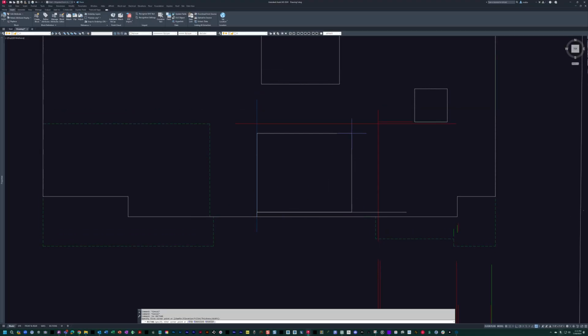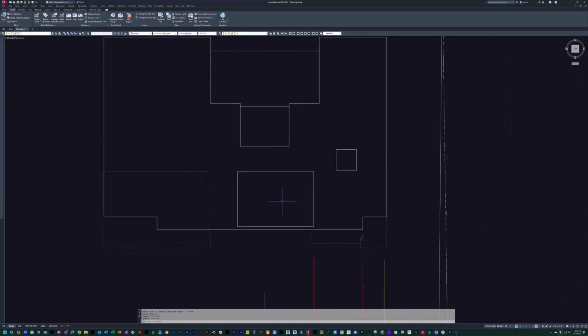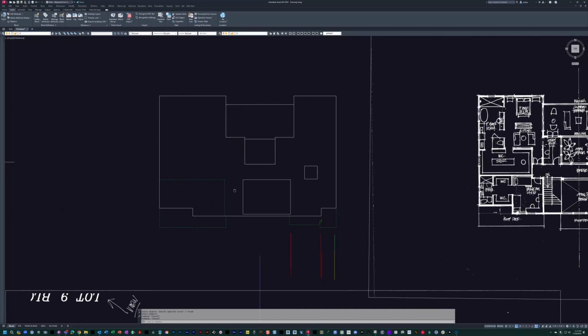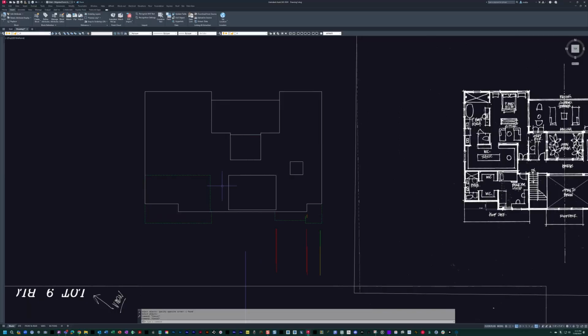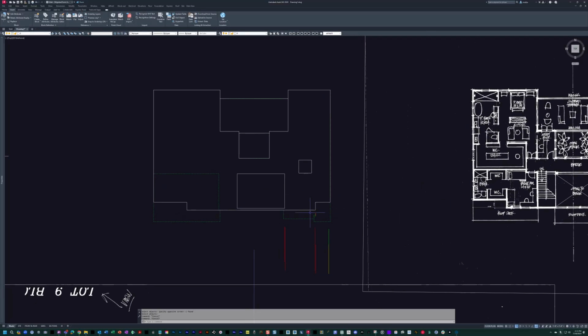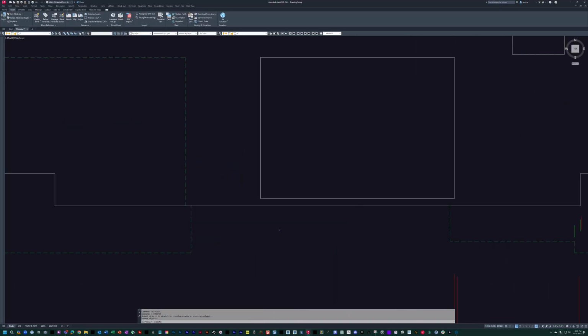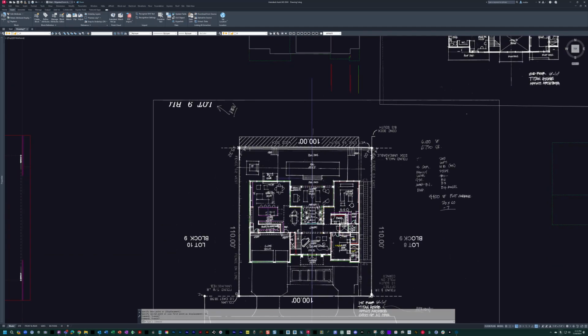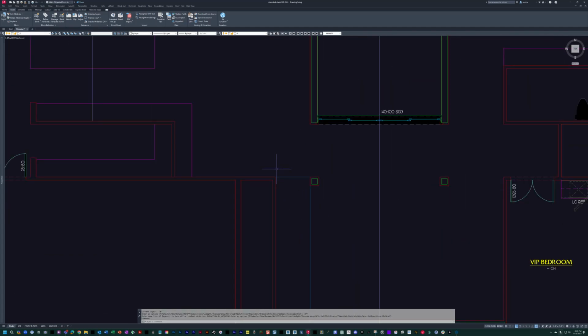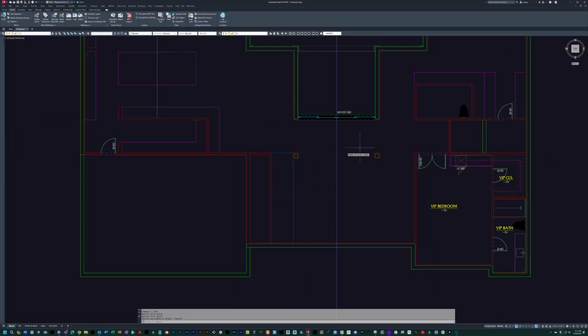So now if I do that, I can get rid of all of these lines, and I know we're going to need this later, but that's fine for right now. So that's the open to below, plus we have the opening for this stair. So I'm going to push this over 48 inches, which will be essentially to this line. And we're going to let that be what's open.